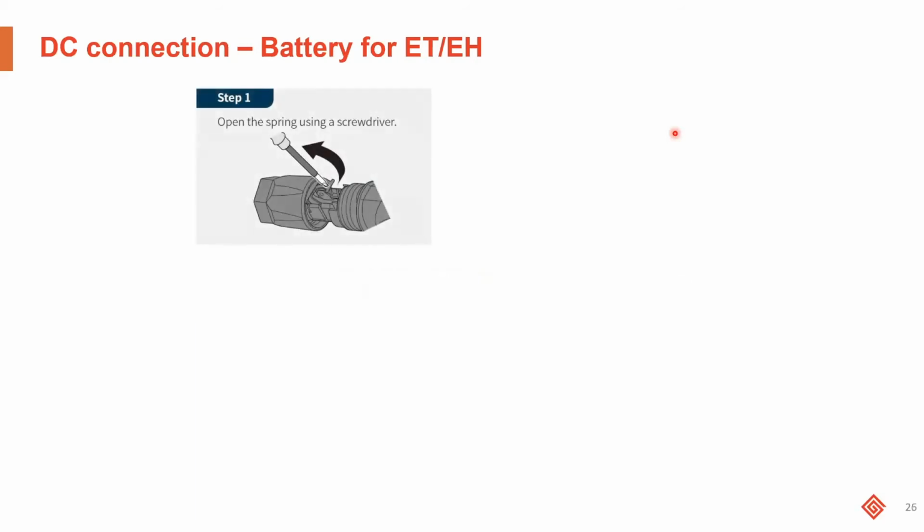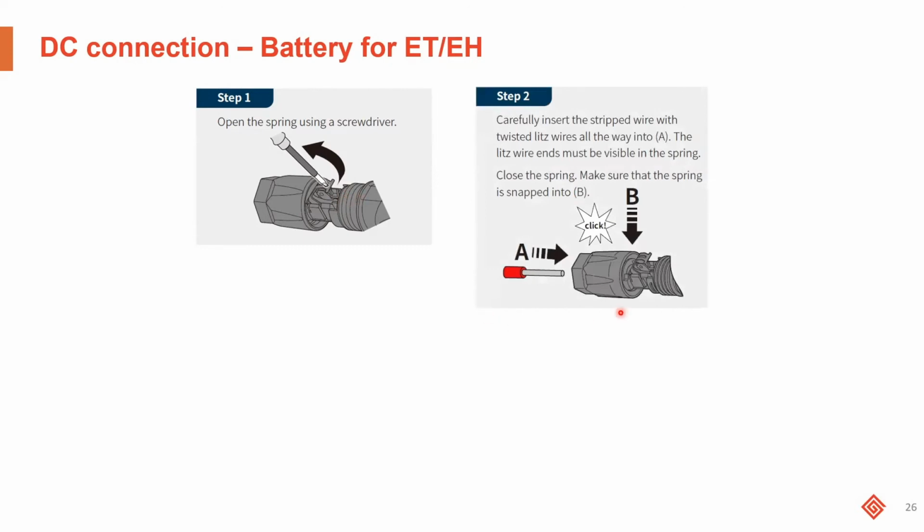If you're not familiar with the Phoenix Contact Sunclix connectors, they're described as a toolless method of connecting DC cables into a PV system. They are supplied with a spring clamp here. All you have to do is strip the cable and insert the cable from one end and then push down.